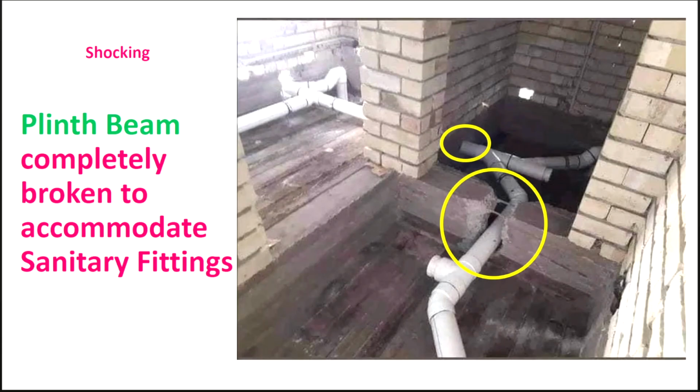Are you able to understand? The structural designer will make a provision of having a 4-inch dia hole in between my structural member. Then possibly, according to design, he will see removing at that particular cross-sectional area from the beam, whether it will be safe or not, or he will increase the section of the beam, or he can provide you an alternative location from which you can take.